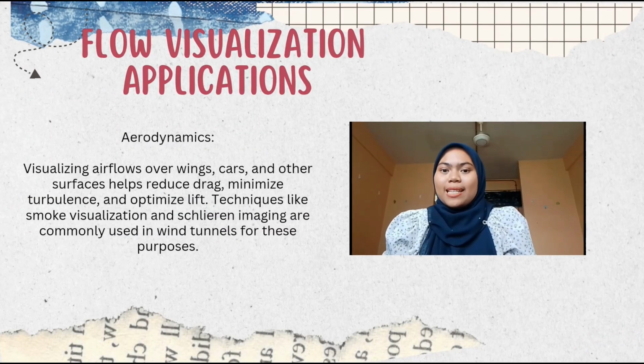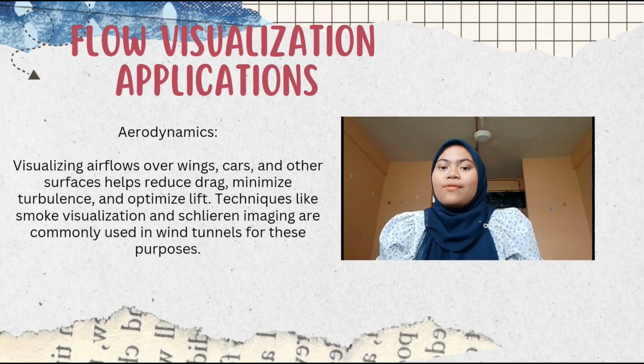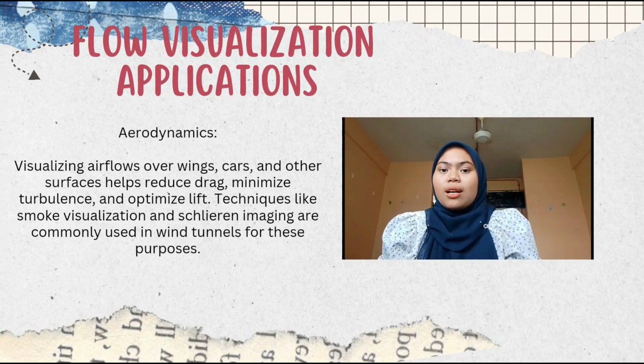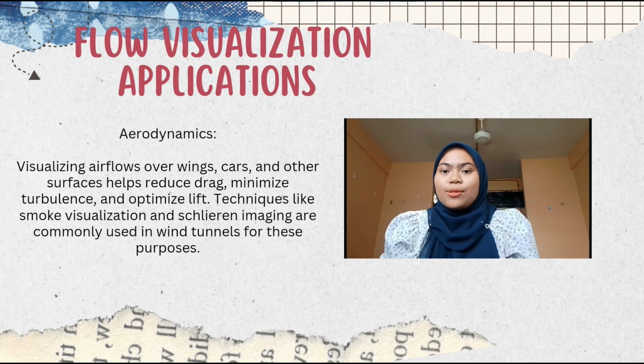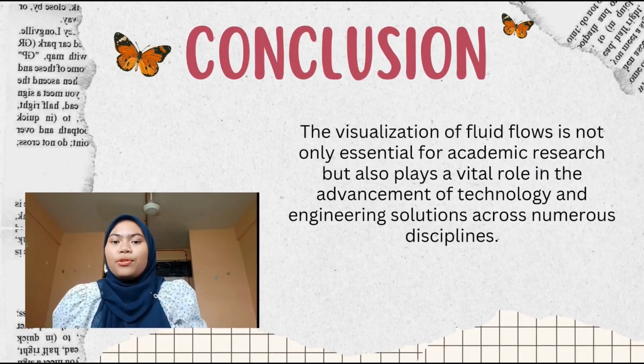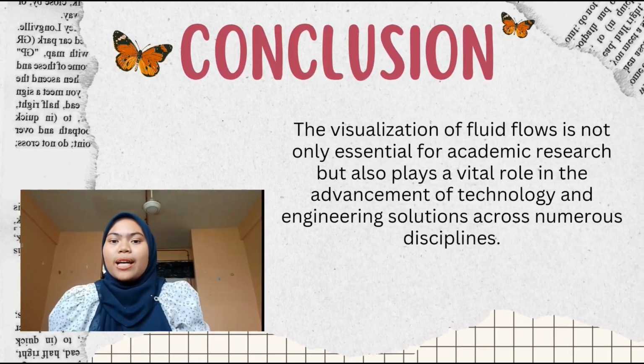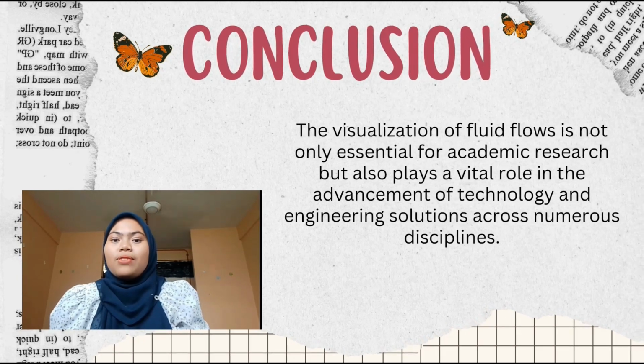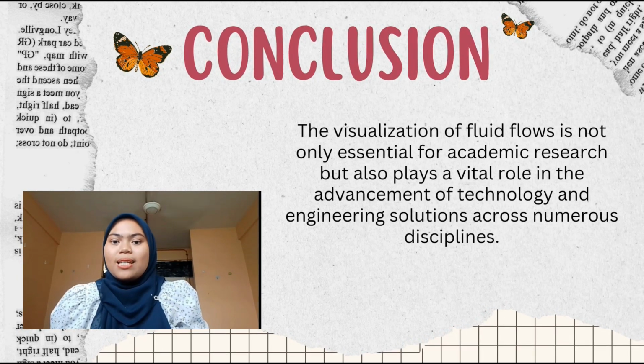Flow visualization application is in hydrodynamics. Visualizing airflow over a wing, car, and other surfaces helps reduce drag, minimize turbulence, and optimize lift. Techniques like smoke visualization and schlieren imaging are commonly used in wind tunnels for this purpose. The conclusion is that the visualization of fluid flow is not only essential for academic research but also plays a vital role in the advancement of technology and engineering solutions across numerous disciplines.